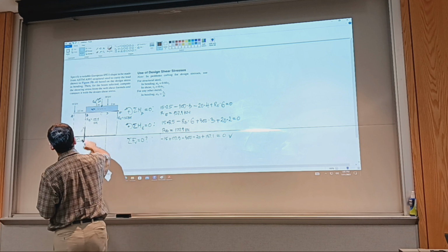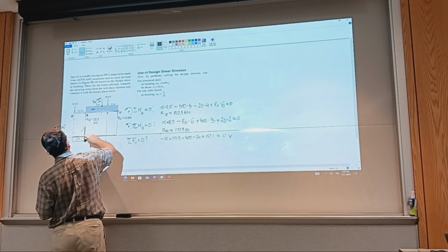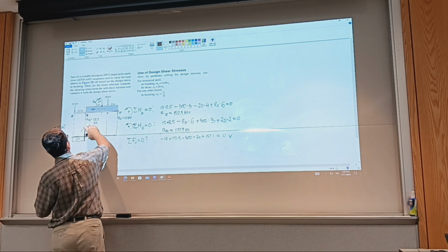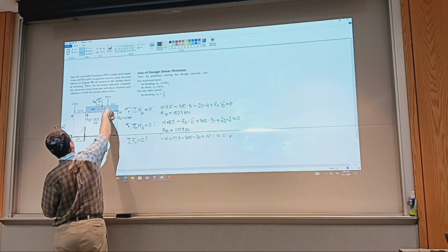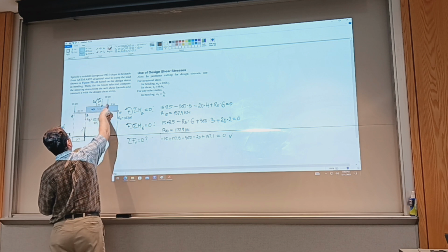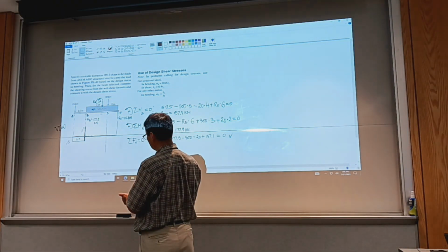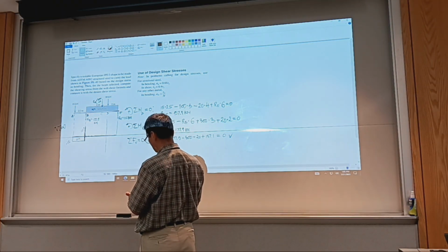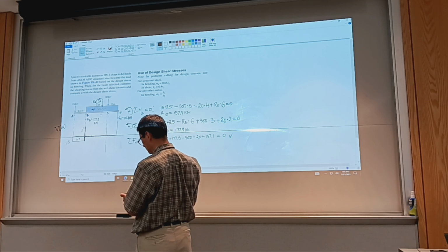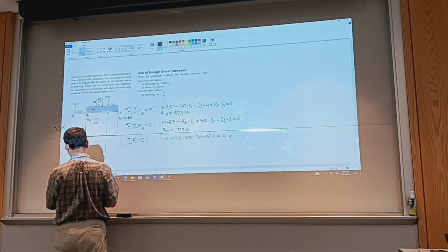All right, so I start here and I go linear. So 162.9 that I have, it's a positive value, I'm adding a negative value, which is the area under the W curve up to point D. So it'll be 162.9 minus 50 times 4 equals, so this went negative to negative 37.1.